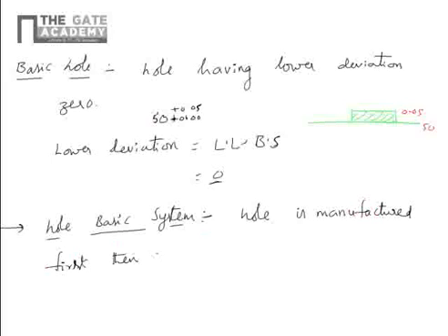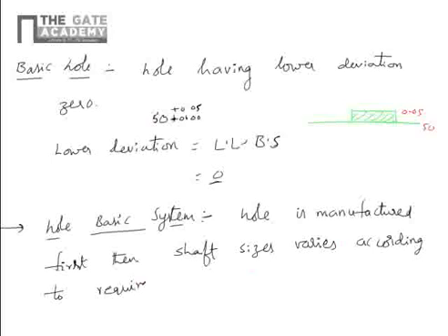Then shaft size varies according to the requirement of the fit, according to the required fit. So it is hole based system. Next, shaft based system.